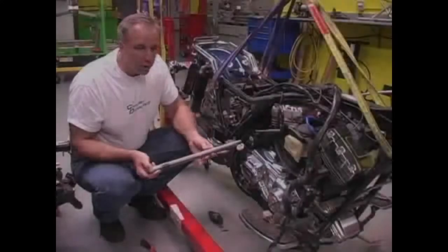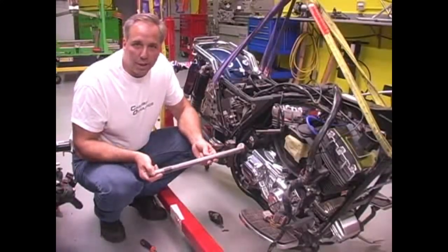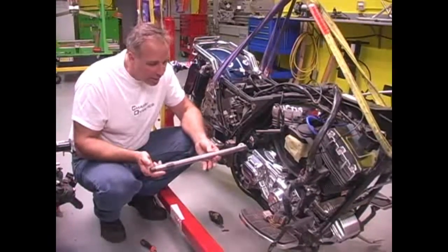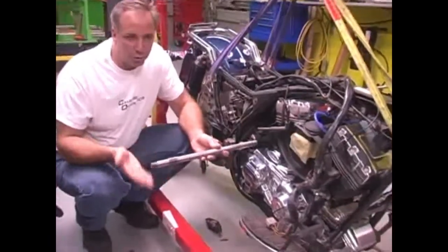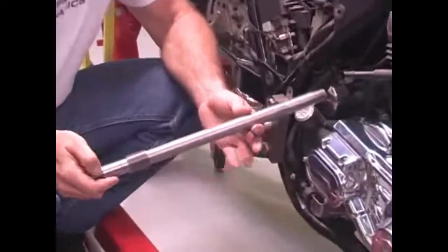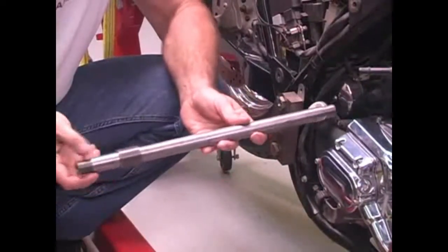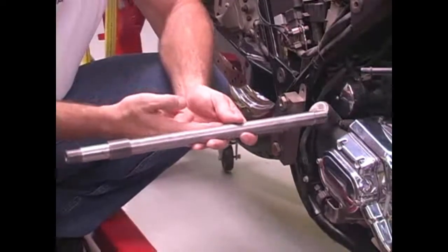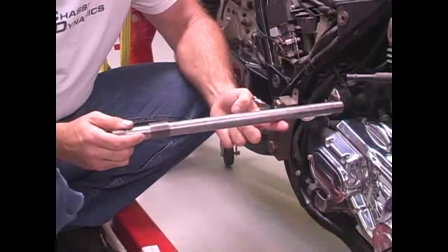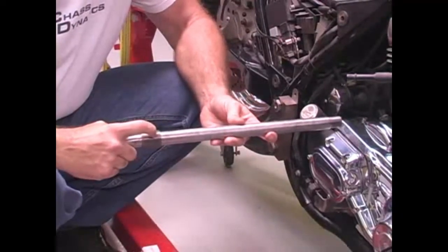So I'd like to talk to you for a moment or two about tooling. This is kind of an interesting setup that we have here today. This would be the tooling for a normal, straightforward GSXR. This is actually a GSXR Japanese bike tooling shaft. And what we do here is typically we would remove the swing arm pivot. This would be inserted into the swing arm pivot. This would be threaded right into the frame.